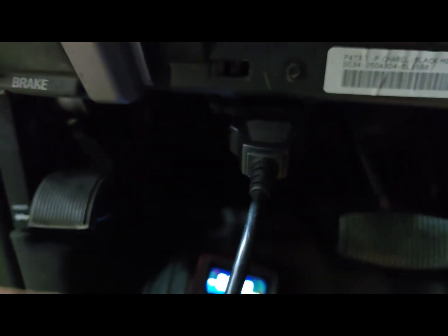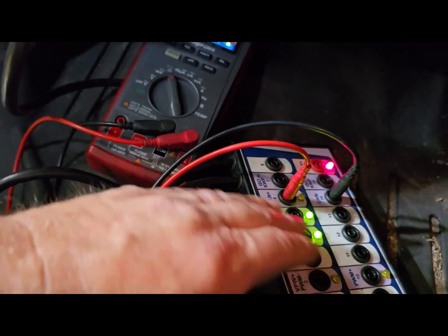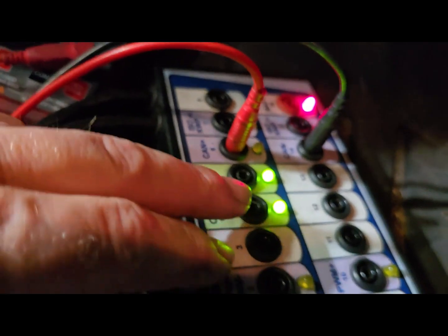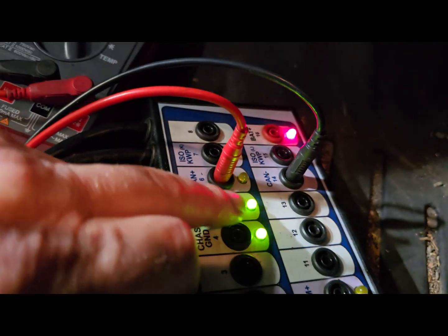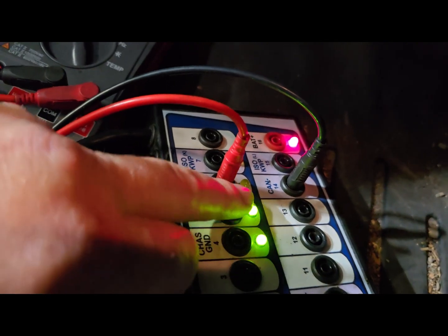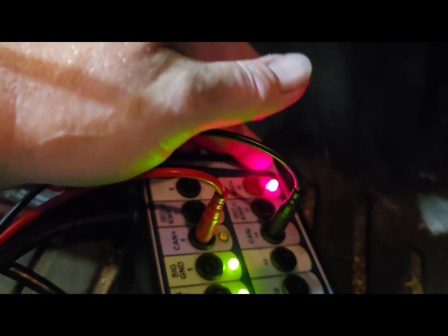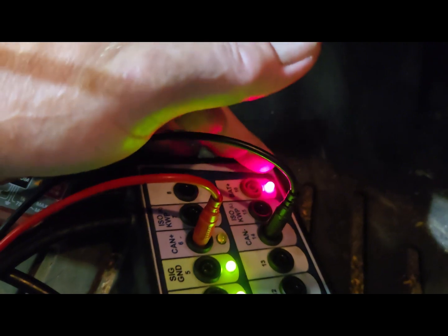So what you do is plug one end into the DLC like that. Then you can have your scan tool plugged into this additional lead, so you can leave your scan tool connected. I've got my top down connected, and you can test everything through this right here. This is nice because pin 4 and 5 are chassis ground, and since there's a nice bright green light, you know we have a good ground. And this red light, which is pin 16, is positive. That's B positive voltage, and we know that's good because we have a very bright light.